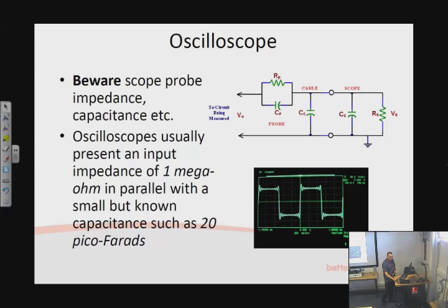We're looking at something there, and of course we've got to bear in mind that potentially some of that corruption, some of that ringing we're seeing there, is due to the very scope that we're connected to. Cast your mind back to that anecdote I gave you in the previous lecture, about the corruption where, ironically, the CMOS gate was overshooting, and the very action of putting my oscilloscope probe on that signal in order to investigate it was curing the problem slightly.